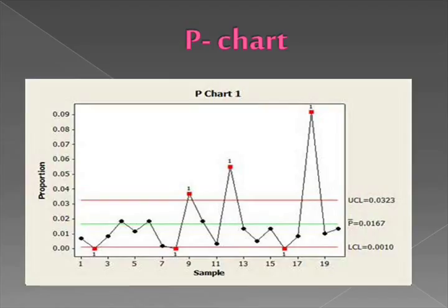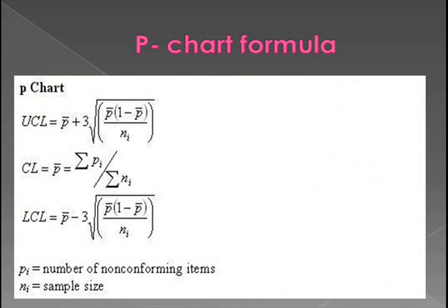The P chart only accommodates pass and fail type inspection as determined by one or more go/no-go tests, effectively applying the specification to the data before they are plotted on the chart. Other types of control charts display the magnitude of the quality characteristic under study, making troubleshooting possible directly from those charts. Here is the formula used to calculate a P chart.